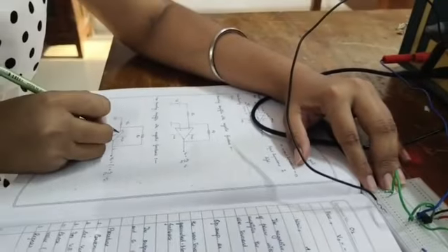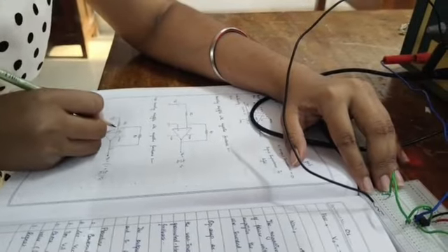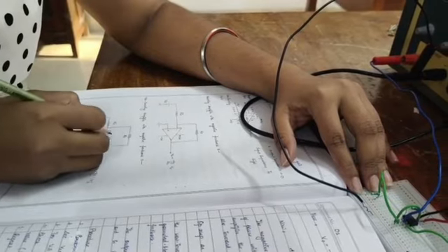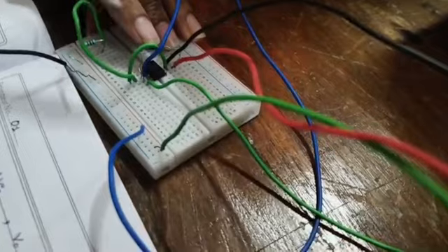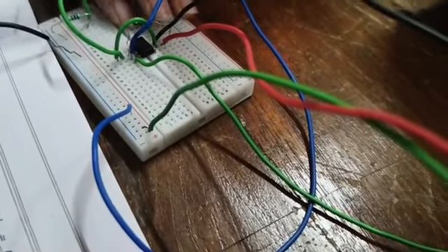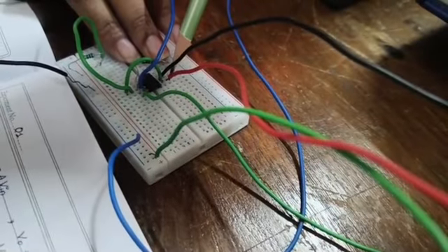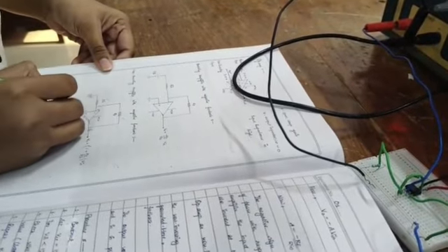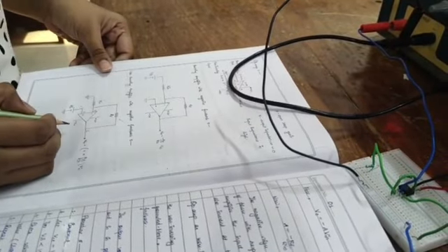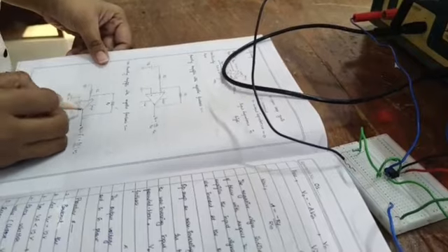Next we have another connection from 2 to 6. That is another resistor RF from 2 to 6. Here, this is the resistance. It is connected from 2 to 6. This is 6. Okay, that is the output. So that connection is also done. Now we have this positive and negative 12 volt.